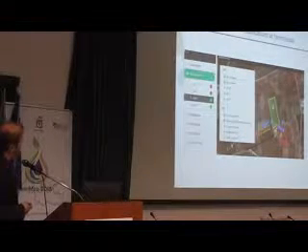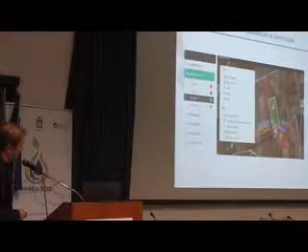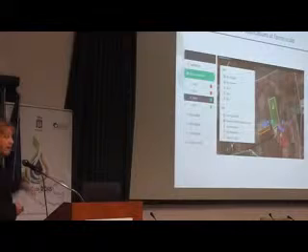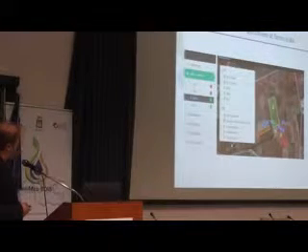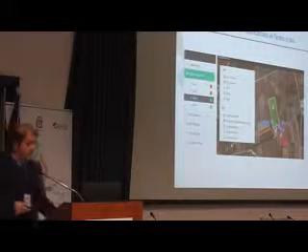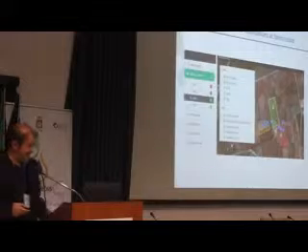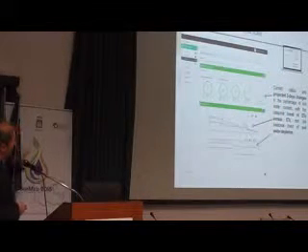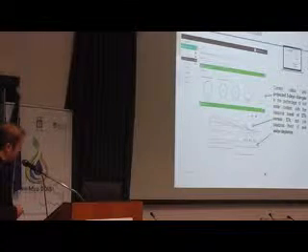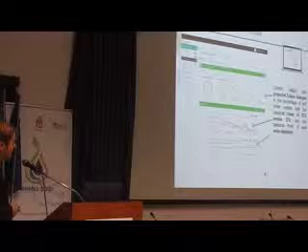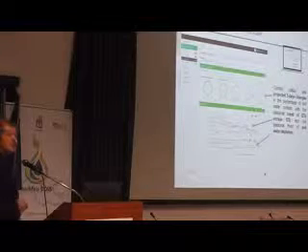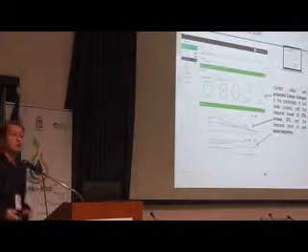Examples of application at farm scale: you see at farm scale we are going to have different details that are related to soil sensors, to weather station, to the main electro well, activating the pumps, and so on. And we are going to go into the system to decide which field is going to be irrigated and when. So, when you go more into details, you are going to see how we are developing soil-water balance. This is the part of the forecasting that is given here. You can understand here that we are entering into water stress, so you can prevent water stress, planning exactly when you would like to have irrigation.